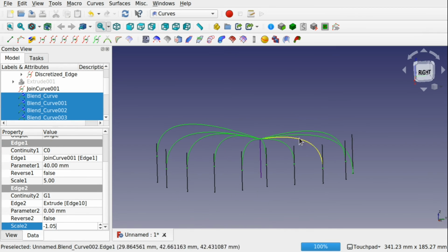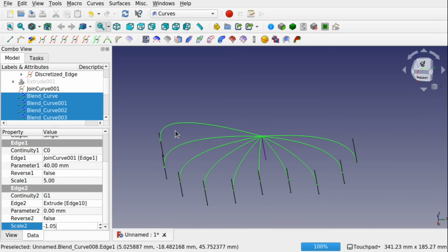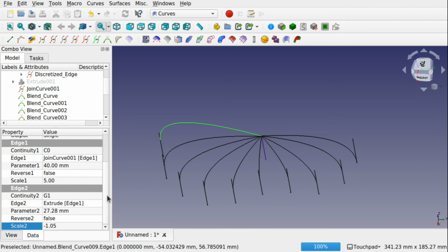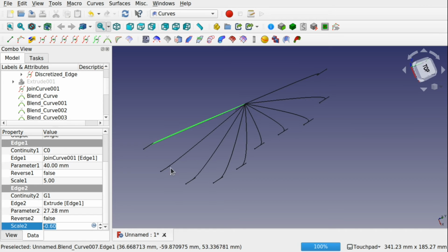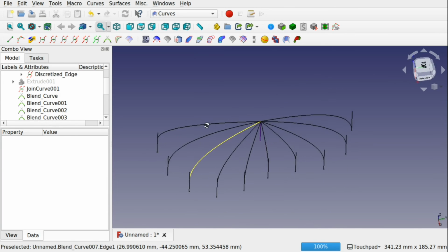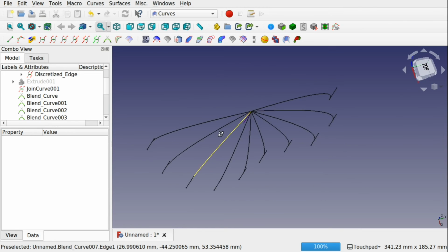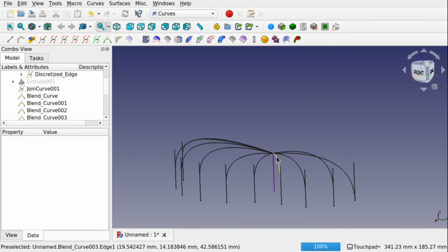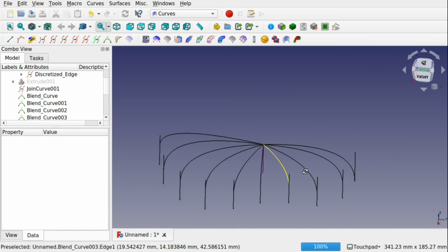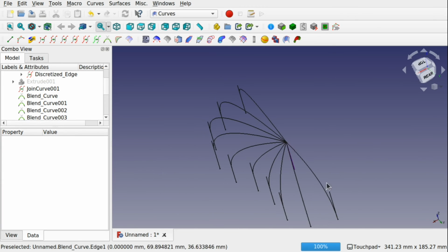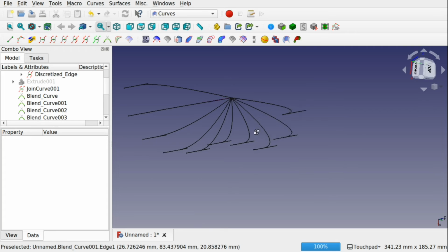And there we've got our surface that's becoming present now. May want to change some of these curves because we're going to get a dip down here. So for instance, this curve, we can scale this whatever way we want. So I'm going to scale this down. Don't worry about this line that's appeared down here. That's just a visual glitch. You can see it's disappeared. And now we have a surface starting to appear, or the start of a surface. These will be all used as profiles.